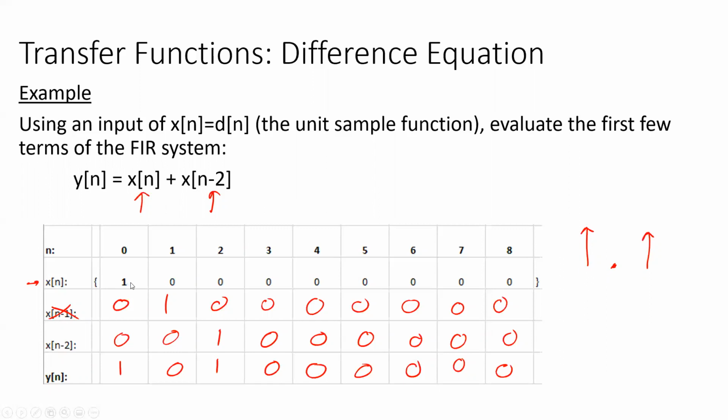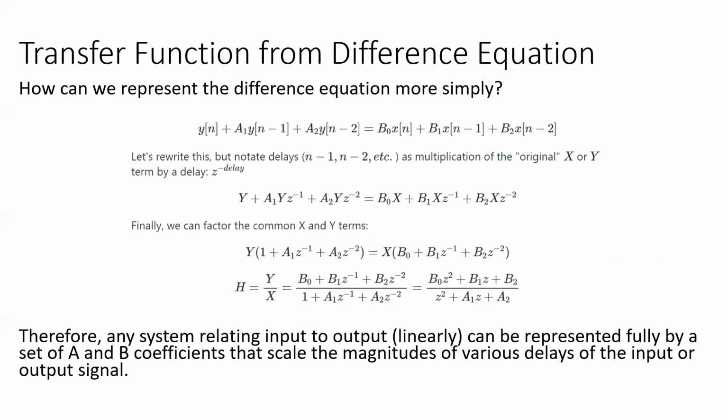It's a 1 here, and it's 0 everywhere else. And then just shift it by 2. You could say that y equals whatever this was 2 pieces ago plus what it is right now. And you can program that in with just some for loops. That's how computers brute force these difference equations. So it's the simplest, easiest way to define a system.